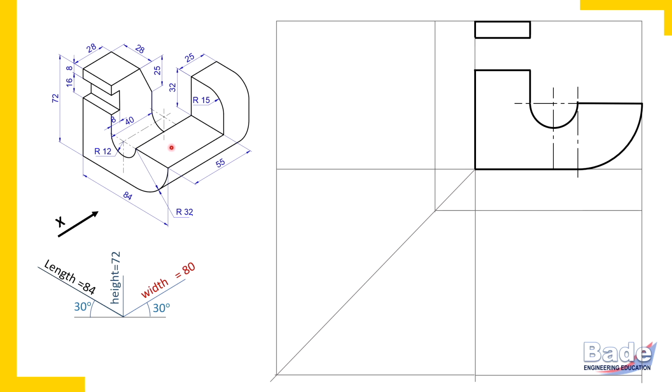Now just check. Do you know where this rectangular surface is in the front view? So try to understand. This surface has two principal edges perpendicular to each other, but one is parallel to width and the other is parallel to length. Which view gives you length and width? Top view. So this surface shows its true shape in the top view.